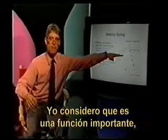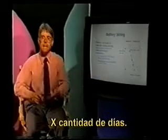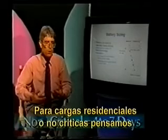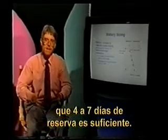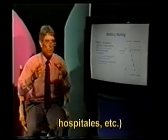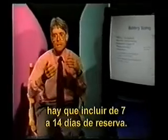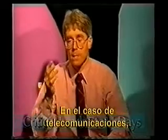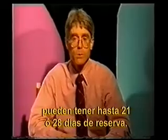So we want to build into our battery bank a number of days of reserve, enough to run all of our loads for a number of days. How many days? It depends on the severity, or the criticality, of your loads. For residential or non-critical kinds of loads, we often think of roughly 4 to 7 days of reserve being enough. For more critical types of loads, telecommunication systems or critical hospital systems, we'd want to build in at least 7 to 14 days of reserve. Very important critical telecommunication systems might have even more than 14 days, 21, 28 days of reserve.